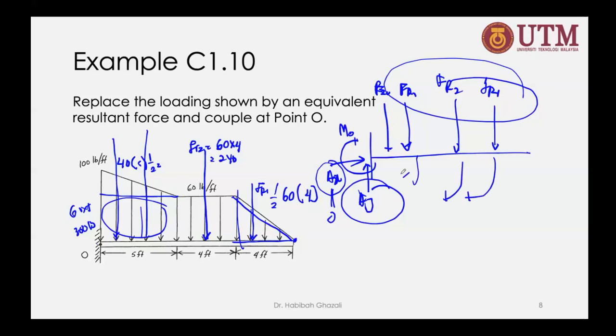And then put your finger in at the pivot point. So here, my pivot point is here. This is my fixed support. So I have forces acting downward, so that is going to cause rotation. It will try to rotate it clockwise. So if your sign convention says positive is anti-clockwise, that is going to be negative.